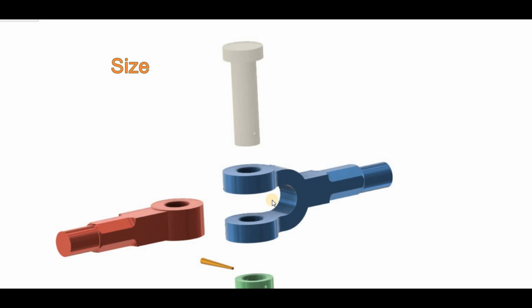Which is also met using the traditional dimensioning method. That is, we can say that the size of this hole should be within a certain amount, or it can cross a certain amount. So this is the tolerance that is already met using traditional dimensioning, which also continues to hold importance in geometric dimensioning and tolerancing.